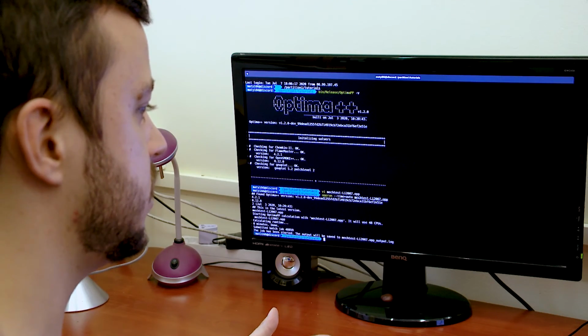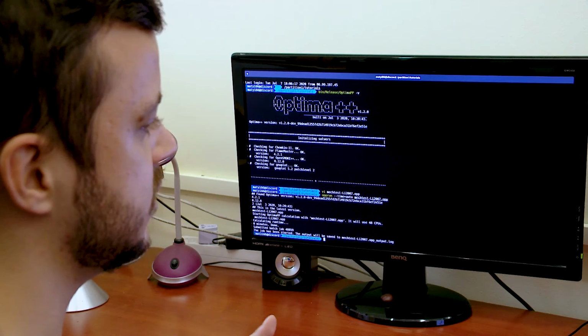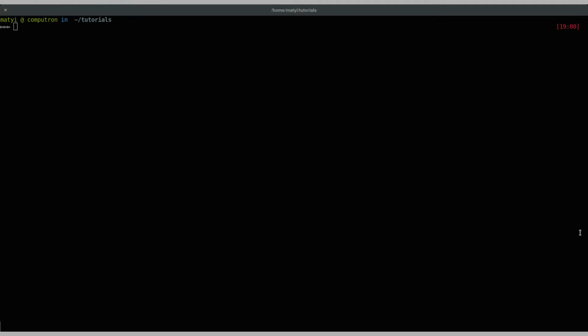You may check the progress of the calculations on the cluster, and when all calculations have been finished, you may process and visualize the simulation results on the host PC. The result files are saved to the output folder. Now I download the content of this folder from the server to my local computer.